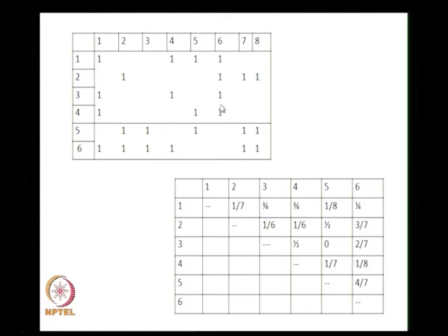If we consider a machine component incidence matrix which is shown here on the top with 6 rows representing 6 machines and 8 columns representing the 8 parts or components, the similarity coefficient matrix can be calculated for both machines or rows as well as for components or columns. The similarity matrix shown in the bottom is calculated for rows or machines, and since there are 6 rows, this is a 6 by 6 matrix. We also explained how these numbers are obtained.